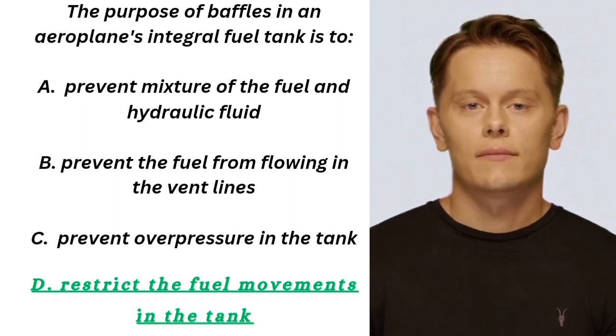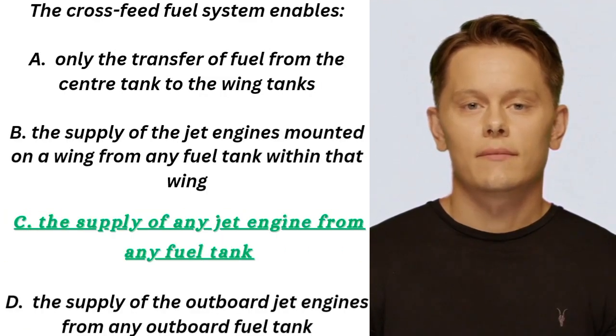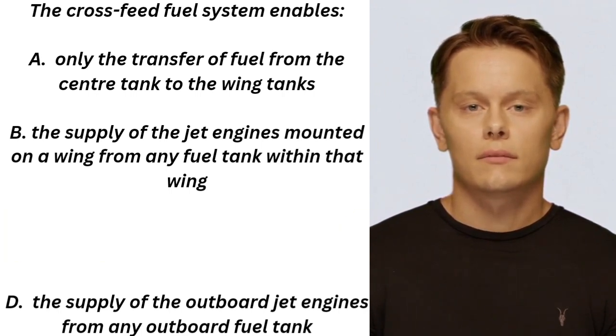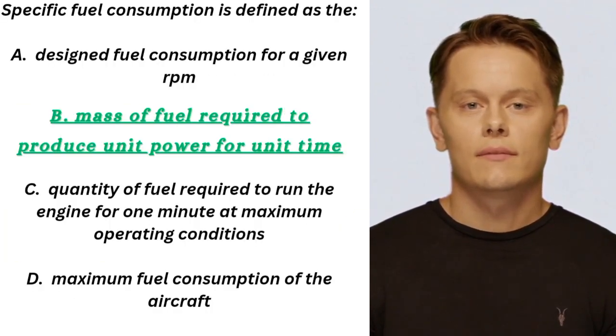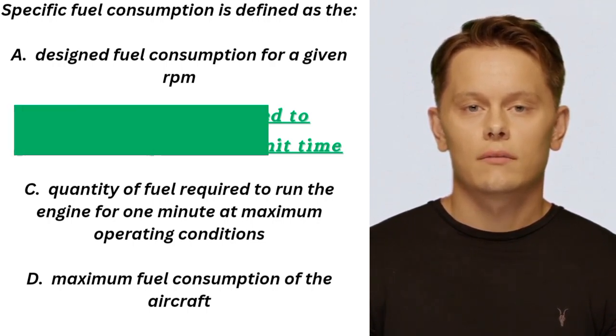Question 41. The purpose of baffles in an aeroplane's integral fuel tank is to. The answer is D. Restrict the fuel movements in the tank. Question 42. The cross-feed fuel system enables. The answer is C. The supply of any jet engine from any fuel tank. Question 43. Specific fuel consumption is defined as the. The answer is B. Mass of fuel required to produce unit power for unit time.